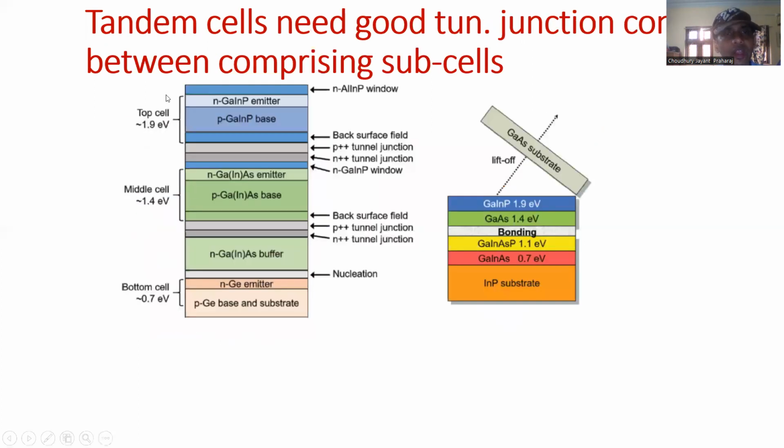This slide shows schematics of tandem cells. Now, this shows a different material system, but the considerations are the same in the indium gallium nitride system also. The important thing to keep in mind is that each subcell needs to be interfaced using these so-called P++ N++ tunnel junctions. These tunnel junctions make sure that there is minimal voltage drop when the photocurrent is flowing in these tandem solar cells.